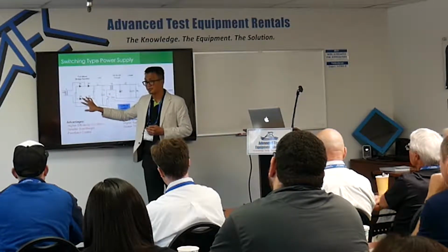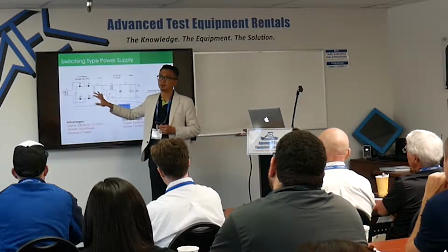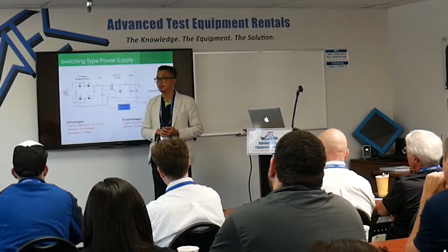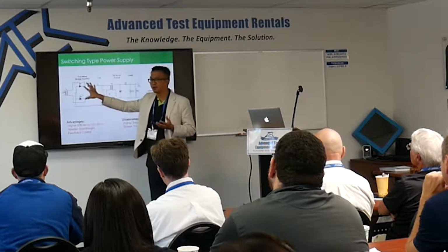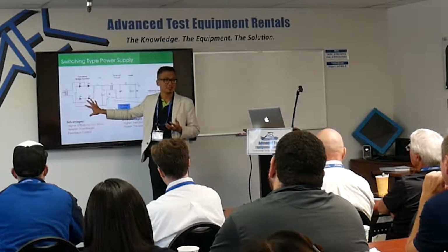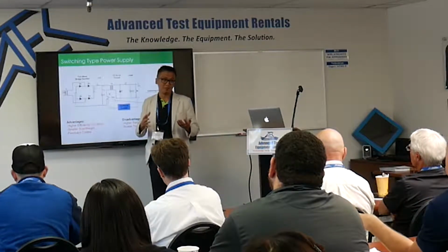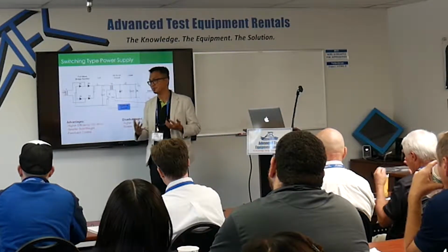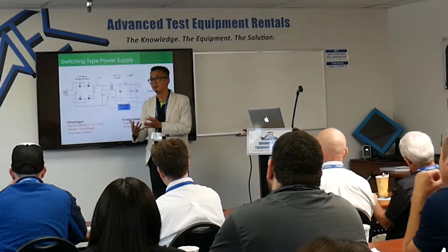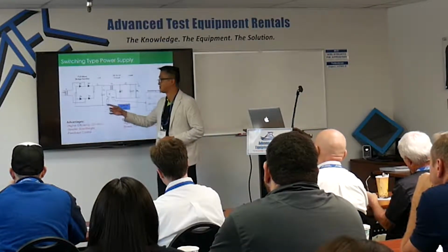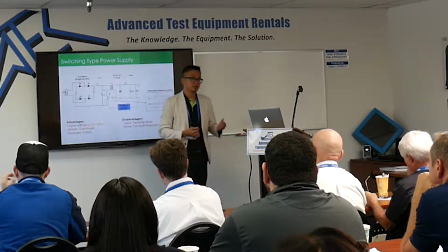So they will do something like a PFC in front, which we call power factor correction. But you can imagine that the more you want to do over here, the higher the cost. So 12 poles will be more expensive than 6 poles, and if you need PFC in front, there'll be even higher cost. So it depends on your applications.